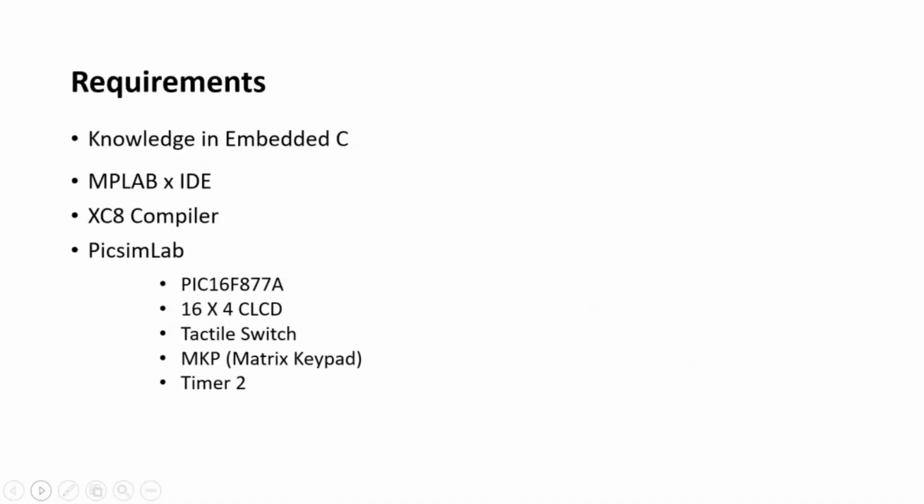Next, there are some requirements for doing this project. First is the knowledge of embedded C, MPLAB IDE for coding, XC8 compiler for the compilation of the program, and PIC-lab. It uses some peripherals like PIC16F877A microcontroller, 16x4 CLCD, tactile switch, matrix keypad and timer 2.